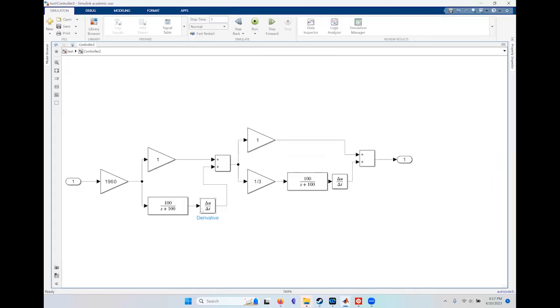And the reason this doesn't make any sense is because it doesn't matter whether we swap those two or not, right? Because blocks are commutative. This is a linear system. Everything is commutative. It doesn't matter if you differentiate and then filter or filter and then differentiate. However, because this is an approximate simulation and the differentiator captures impulses,